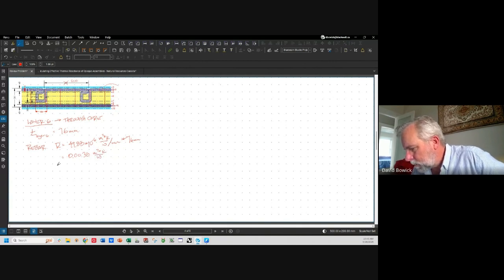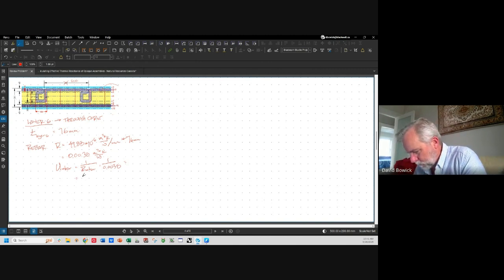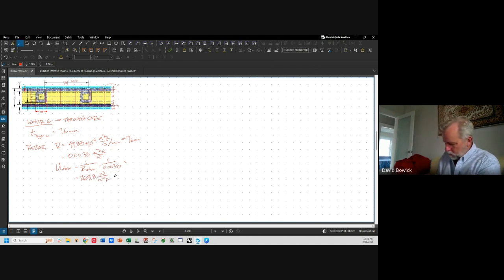So U rebar equals 1 over R rebar, 1 over 0.0038, equals 263.8 watts per meter squared, degree Kelvin. 1 divided by 0.0038 is 263.